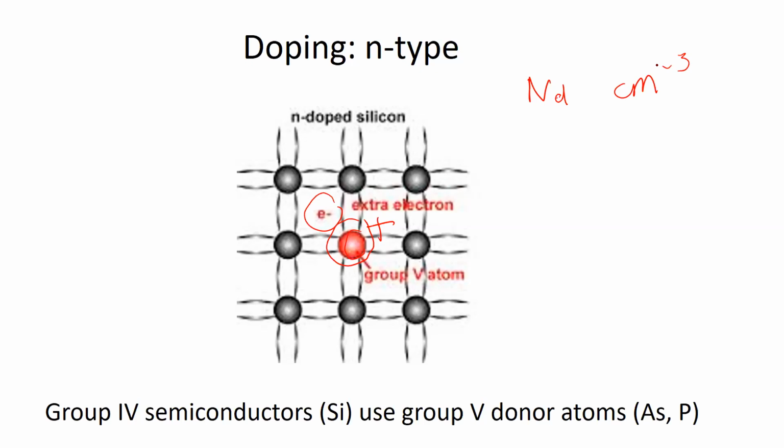All concentrations in semiconductor devices are quantified as densities in cubic centimetres. So it will make sense when we do our calculations to use centimetres for all the parameters, including dimensions. This does require quite a lot of conversion of units, because most devices are much smaller than centimetres. But it also makes sense to use centimetres because carrier mobilities are also generally given as centimetres squared per volt second.